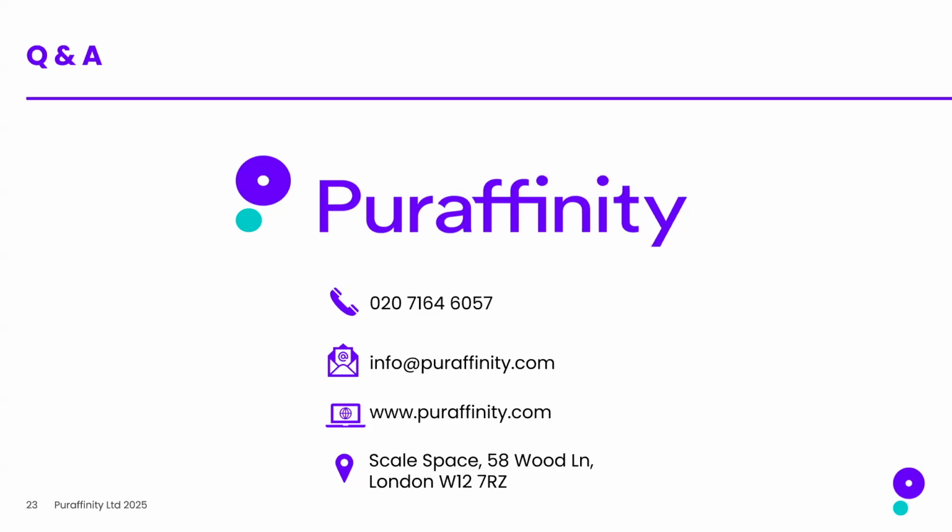It's a different thing. You have people that have been using activated carbon to remove other compounds in the water, like chlorinated solvents, where the carbon lasts a year, and now all of a sudden they're getting PFAS at ppt levels, and in theory may have to change the carbon out in 3 to 4 months. It's certainly making the industry look at some things and figure out what's the best way to solve them.